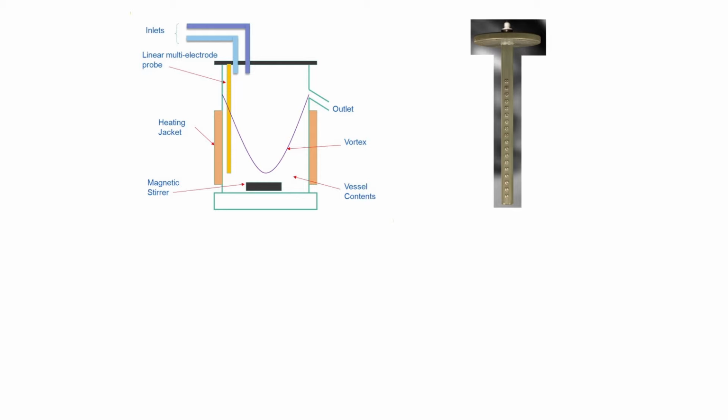We can set the impeller at a slow speed of 200 revolutions per minute and use the probe data to derive an image using appropriate software. The resulting tomographic image is valid for an approximate region up to the vessel centerline, as illustrated by overlaying the actual image on the diagram. We see no discernible vortex at the slow speed.